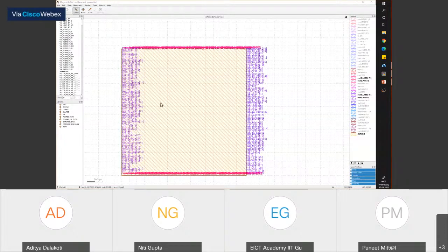In any tool environment, you have some commands which go and source some scripts, and those scripts do certain functions. Now, instead of this place IO command, I will later show you that you could have run a superset of those commands. We ran init floorplan, place IO, PDNGen, and all those things. There is a superset of these commands.